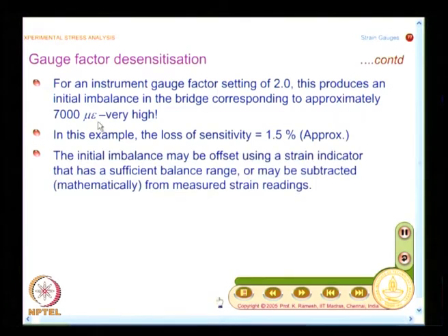And we have already seen in the case of most engineering materials, at 0.2% strain the material yields, 0.2% is 2000 micro strain. So, you will never go to 7000 micro strains unless I am looking at some plastic deformation and so on. So, my measurement range will be much smaller. This is where you have to keep in mind, in strain gauge instrumentation you are measuring quantities of the order of 10 power minus 6. Though 1.7 ohms looks much smaller in comparison to 120 ohms, this is very significant from strain gauge instrumentation point of view.